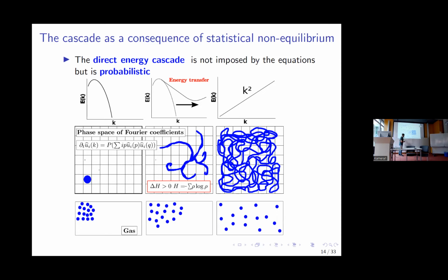Energy density is related to that. Fourier space is three-dimensional, and the spectrum is calculated over something that has an area that goes like k squared. That's why you get a k squared. That's the definition of the 3D energy spectrum. If you do 1D, it's a different thing.